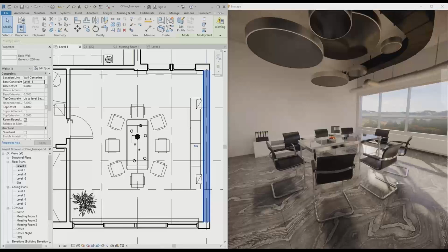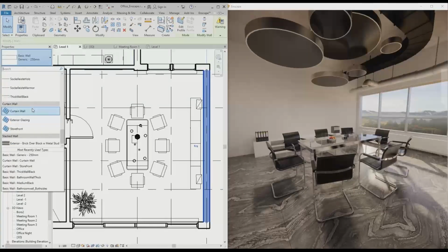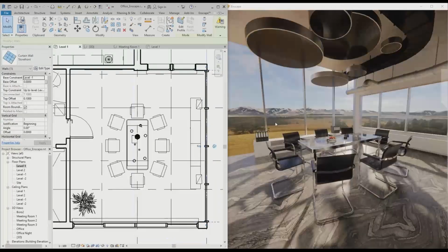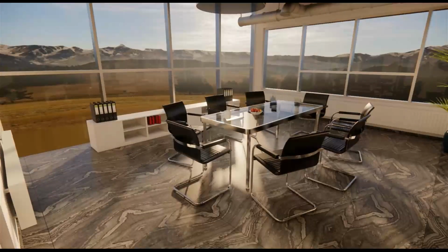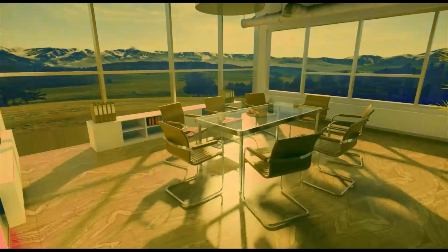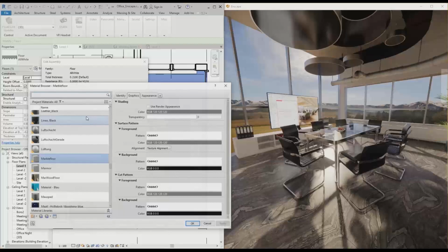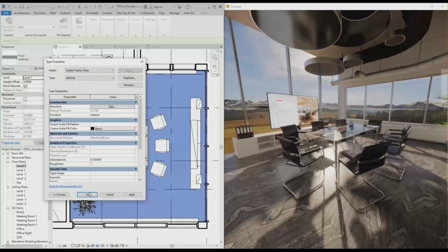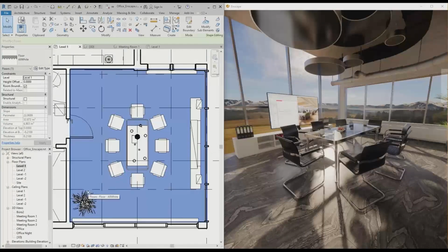So we're really doing exactly what we talked about in that example right here. We've got Revit open, and we've just changed the solid wall to a transparent curtain wall, and all of a sudden we can see how the lighting level is changing in the space. We can see what impact that has. It's obviously a lot more light, and so therefore now we're going to respond to that change by changing the material of our floor, and we've gone from this tile to this wood now, and we can see that the light is interacting with it in a completely different way.